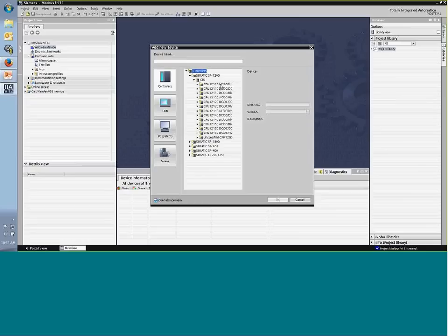In case of AC, it is AC powered, 120 or 230, and on DC, it's 24 volt DC powered. The second, DC, stands for what kind of inputs there are. They are all DC inputs, which can be NPN or PNP, depending on how you jumper the pins. And the last one is the outputs, which could be either relay outputs or DC 24 volt outputs.